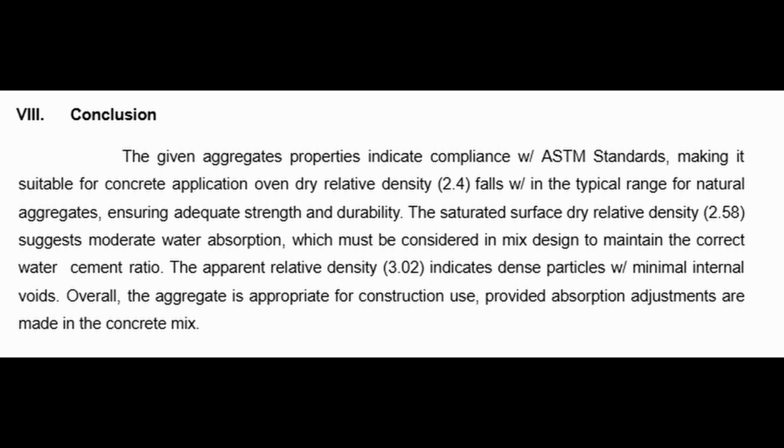The apparent relative density, which is 3.02, indicates dense particles with minimal internal voids. Overall, the aggregate is appropriate for construction use, provided absorption adjustments are made in the concrete mix.